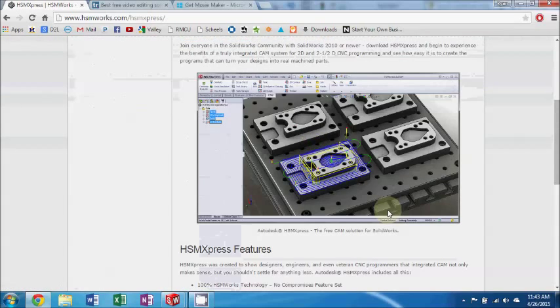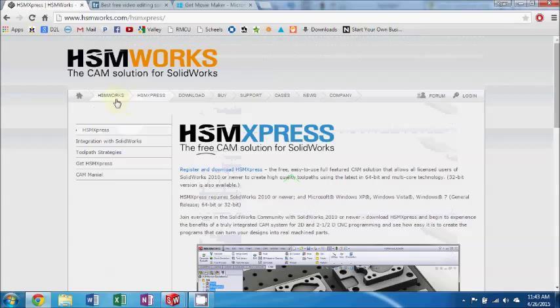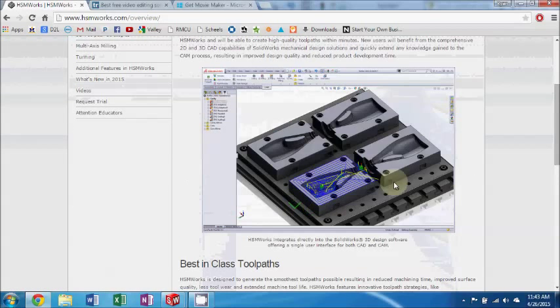Well, what that means is that you can essentially machine things that are on an XY plane, on a two-dimensional plane, that have a depth associated with them. So the picture that you're seeing on the screen right now, that's a perfect example of a 2.5D machining process. As you can see, all these contours can be drawn on a plane, and there's just simply a depth that's associated with them. A 3D machining solution would be something that essentially is a true generated surface that can't be modeled on an XY plane, such as this bottle right here.